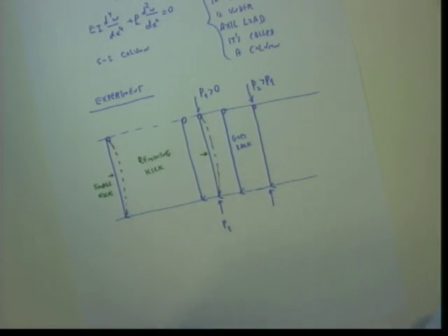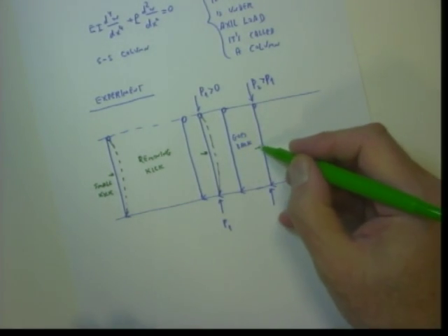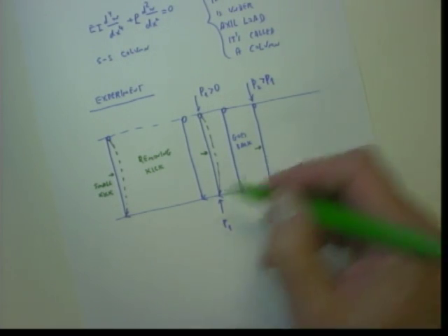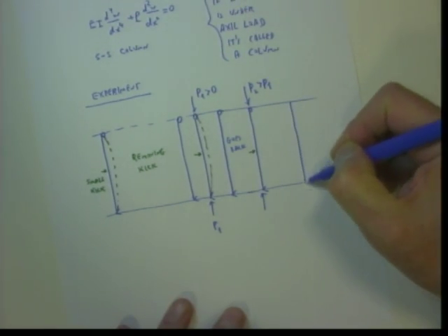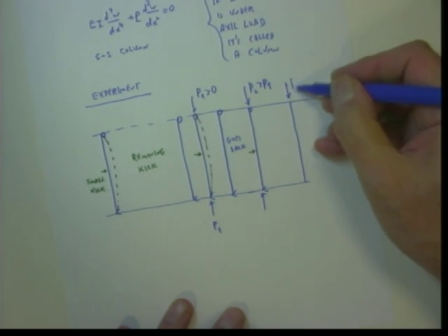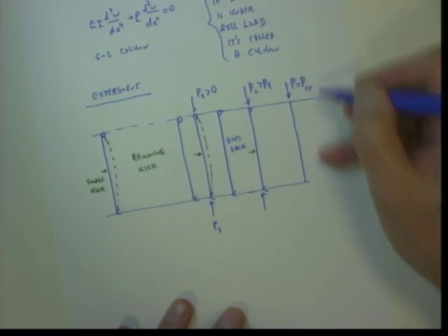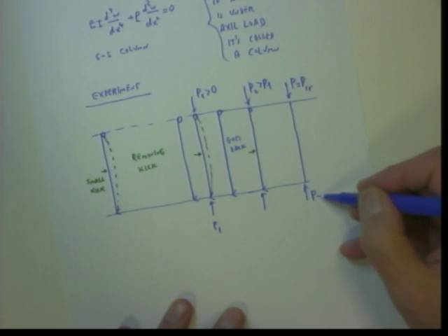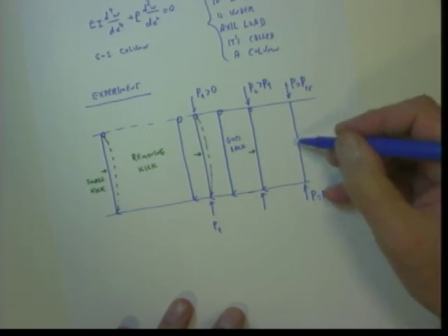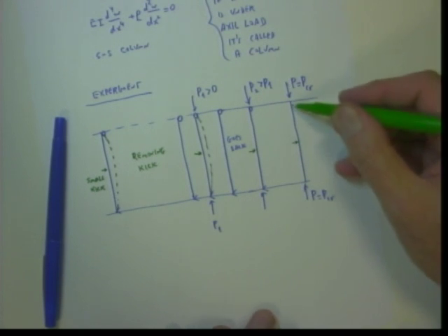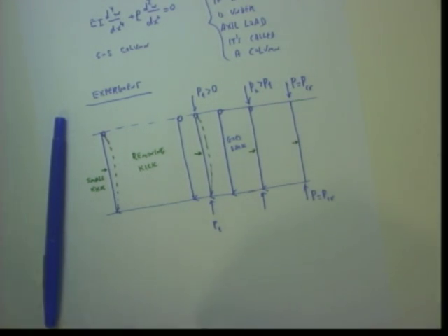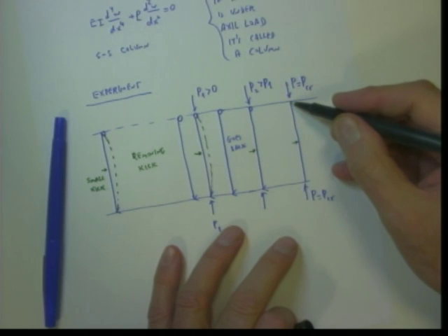Okay? And I'm giving a kick, etc. So we are doing this experiment until we are getting to some position. So this P equals P critical, such that there is some small kick, but the column does not go back into the original position.